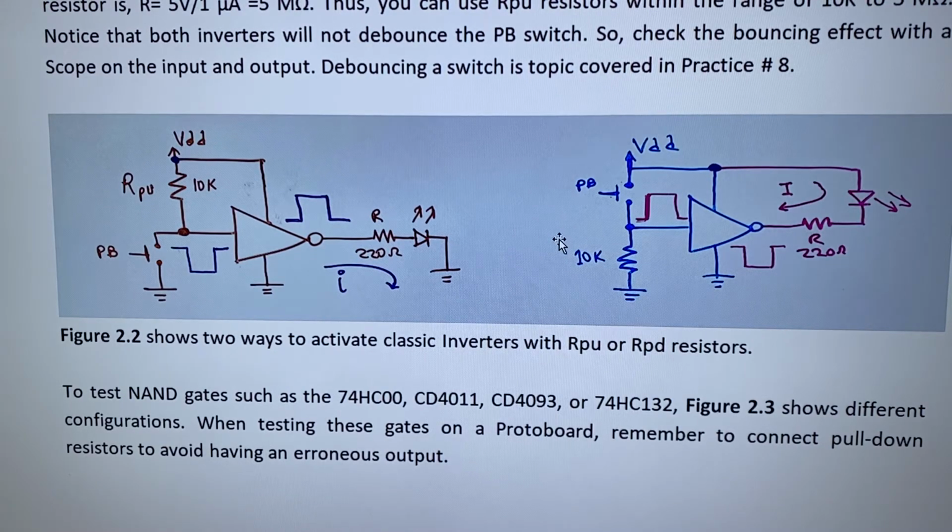And these inputs might be affected by electrostatic charge. So if you don't put a pull down resistor or pull up, when you approach your hand, because of the electrostatic charge that you have in your body, the inputs will be charged, will be receiving a voltage, and it will not work well. So we don't want inputs to float. They always have to be grounded, or go into voltage with a pull-up resistor.